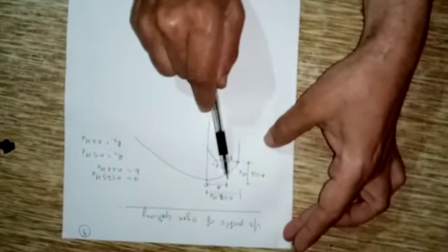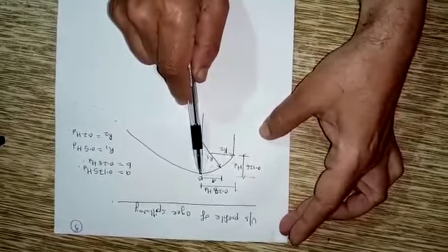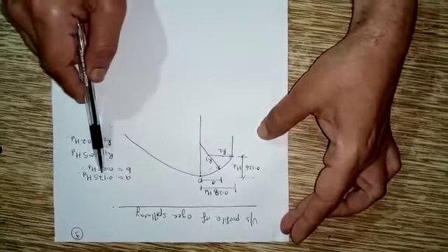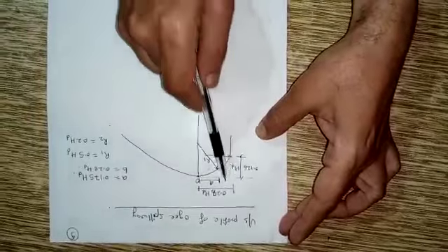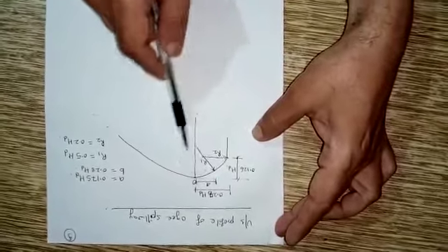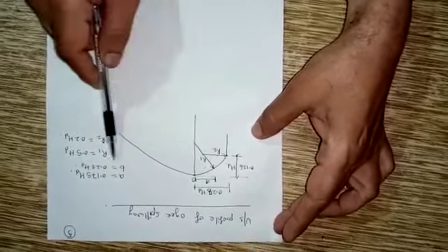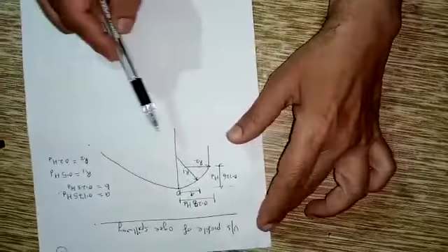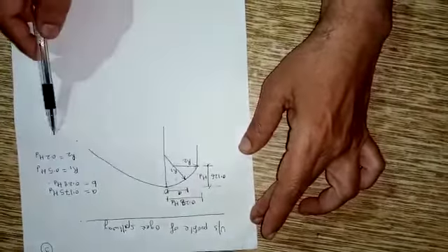The distance A from the point O, that is the crest of the spillway, for the first curve is given as 0.175 HD, and the distance B of the end of the upstream profile is given as 0.28 HD. Thus, using these equations, the upstream profile can be designed.